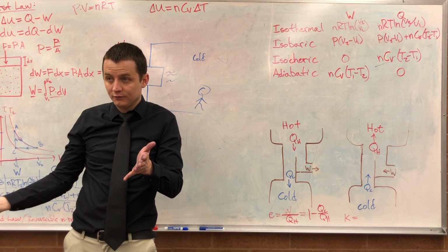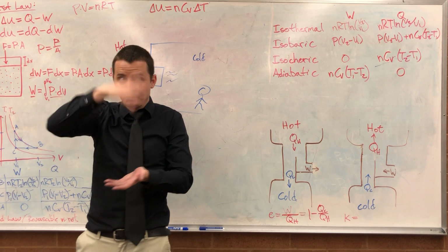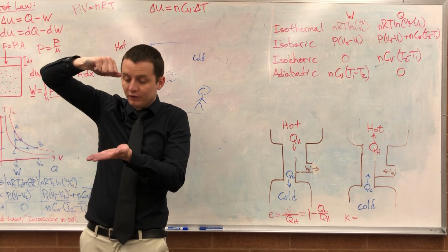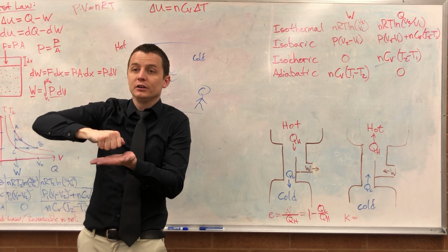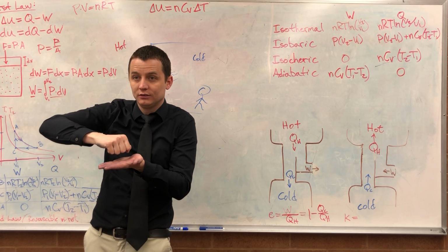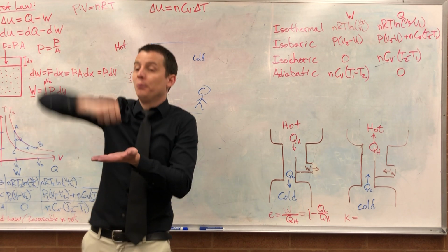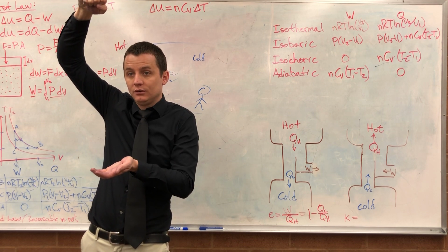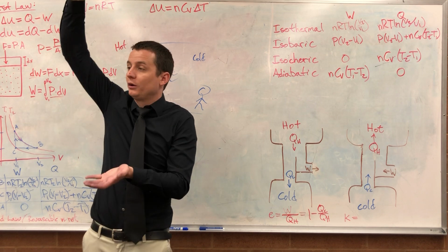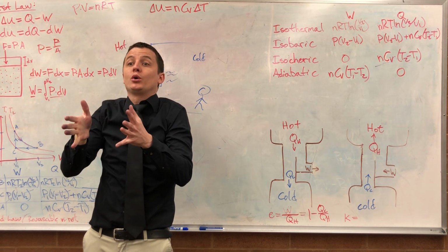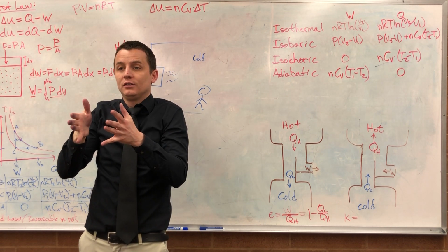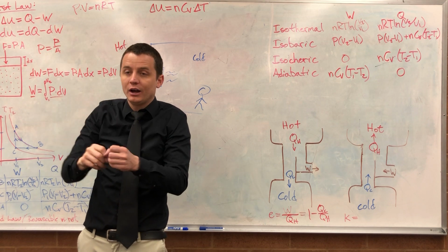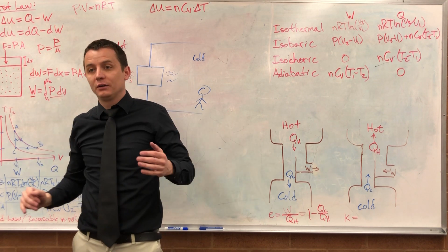Or just think about a gas and piston. We've kind of already talked about this. If I've got a gas and piston, and I push down really fast, the gas heats up. And if I pull really hard, the gas is getting cooled down inside. If I pull and the gas cools down, it will want to absorb heat from the area around it. If I push down really fast and it heats up, the heat's going to want to leave and go to the area around it.